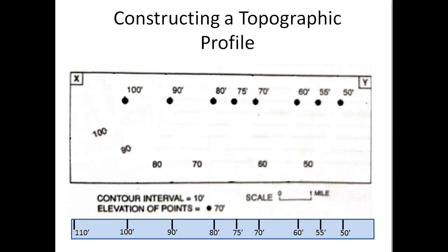In order to analyze the impacts of a spill or leak on groundwater, a scientist will need to analyze the topography of the area. They may start by obtaining a standard topographic or contour map of the site area. Elevations at the Earth's surface are depicted on topographic maps by means of lines of equal elevations called contours. So these contour lines are going to then indicate areas where we have equal elevations.